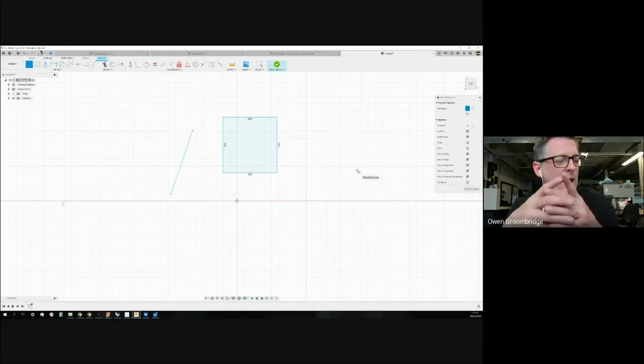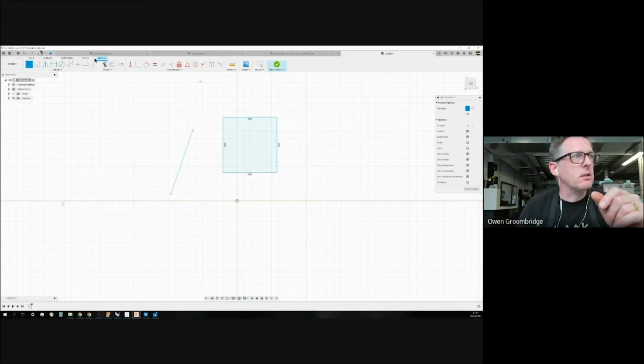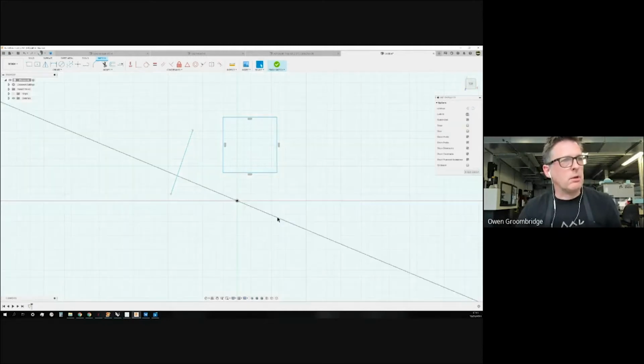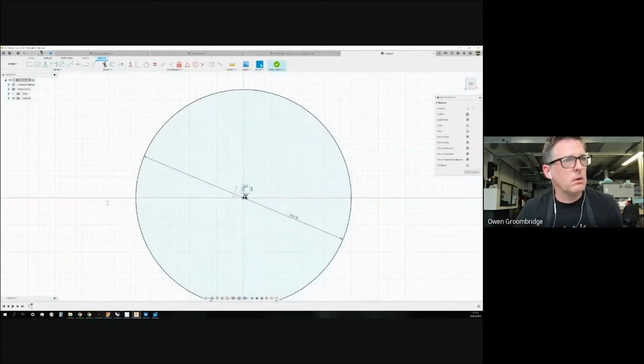Now, what happens is that when it does become constrained, for example, if I draw a circle right on that datum point, I put that in there, and then I enter a number, which in this case would be 20. Is that okay? Let's zoom out. That has got a black line. It's got a center, it can be referenced, and it has a dimension.